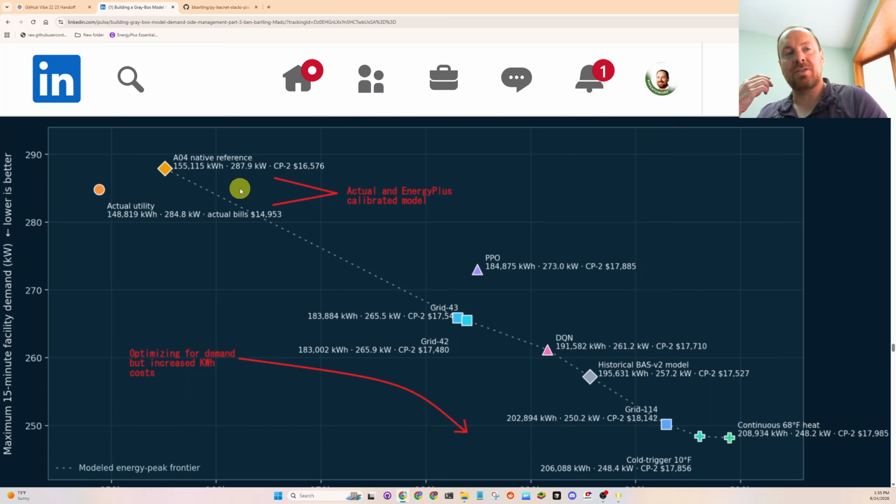And then what I wanted the artificial intelligence to do, including grid search, was, I should have kept that other window open, to increase the runtime with the idea that you lower demand. When you increase the runtime, even run the building 24/7, which is a really common practice in building operations, which I think people do too much, they're kind of scared of it. They do it for temperature complaints, but what I wanted to do it for was to reduce demand charges.